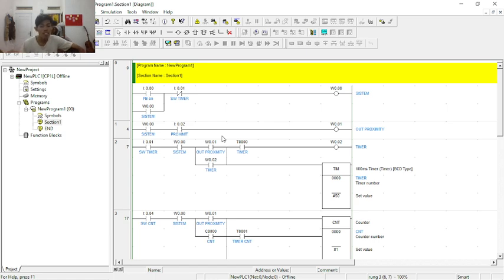The PLC activates the output coil that drives the solenoid valve, and the pneumatic cylinder expands. When we remove the metal object, the signal goes off and the cylinder retracts. So when we execute this diagram on the real PLC, it will show how the proximity sensor and PLC ladder logic work together to control pneumatic motion automatically.